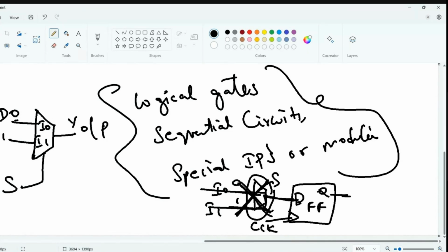We will not have any such conditions in real time. This race condition is from long back when RTL engineers were not efficient. They used to write like this. So we used to have tri-state bus or different ways out to get rid of this. If somebody has written it and later we can't change it, then we add one more logic or delays to the paths. So the best solution is adding a mux. So you select only one path at a time.